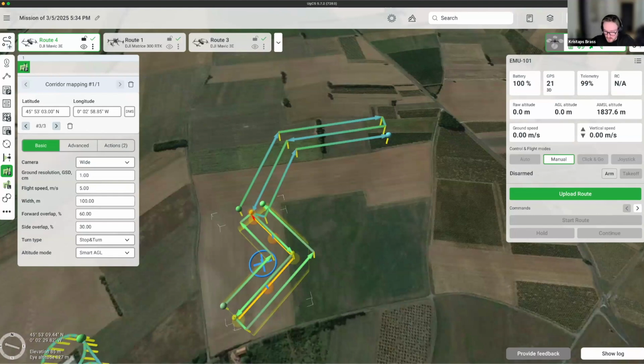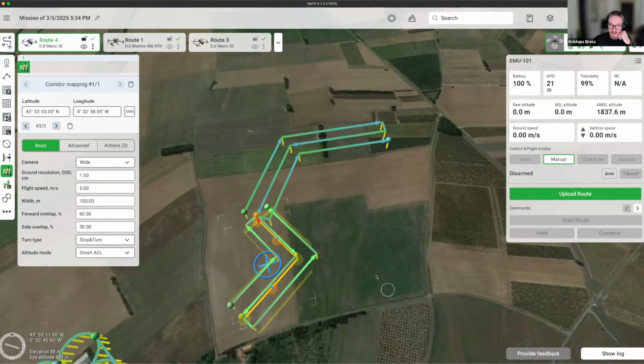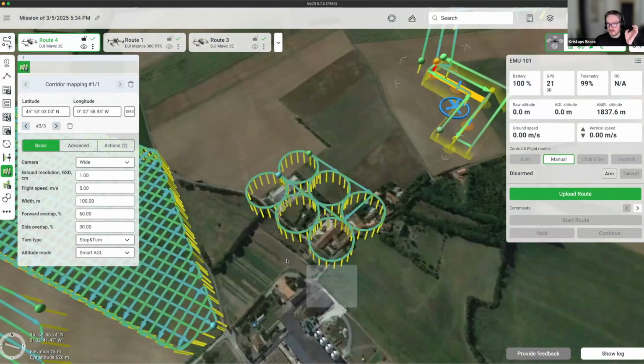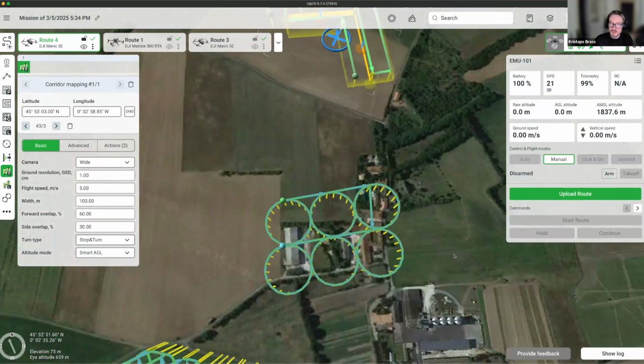Then I see another question is about 3D models generated with circlegrammetry and how they compare to your standard oblique and smart oblique missions. Smart Oblique depends on what drone you are using. But for example, one thing I've noticed in the case of Mavic 3 Enterprise and Circlegrammetry is that if you need to cover a limited area where you cannot really fly outside of it, circlegrammetry is usually a better approach.